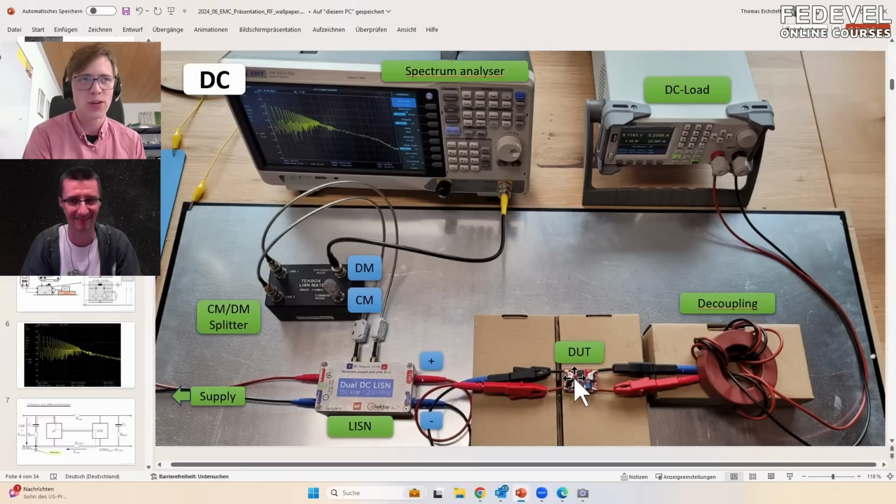And it's actually always going with the path of the lowest impedance, which means it's going as close as possible under the lines, so that you are minimizing the inductance. This is always what the current is doing.